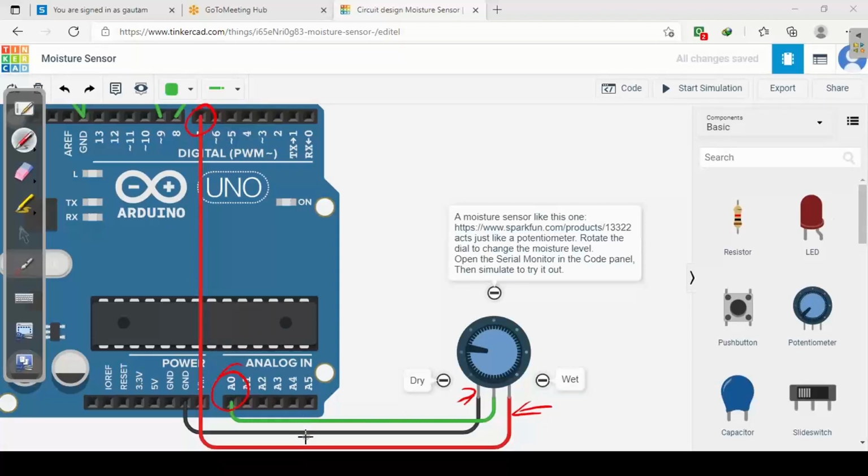So generally, if you connect it to VCC, at that time your potentiometer will be activated and will be working. But suppose you want to control the ADC value generated by this potentiometer, then it is better to connect it to a channel. So as you can see here, I've connected to channel number 7. Now at channel number 7, if I pass 5 volt, then this potentiometer will be activated. And if I am passing 0 volt, then this potentiometer will be deactivated. I hope you're getting my point. Clear to all of you? So this part should be clear to everyone.